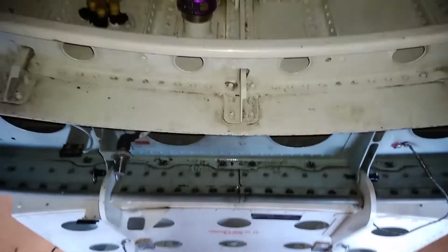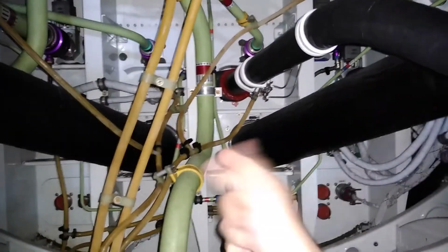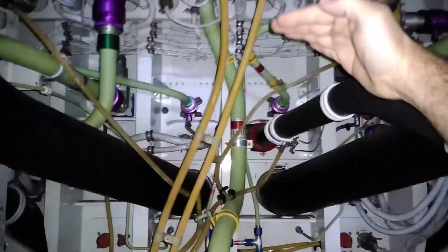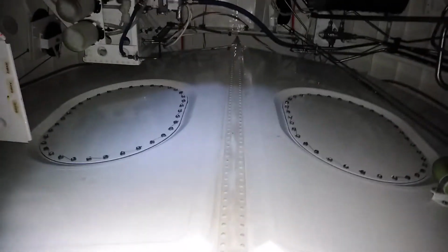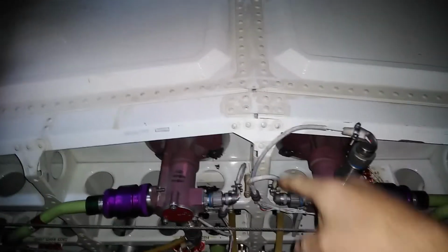Alright. Now we're looking forward again. We are inside of the aft equipment bay, up a ladder. This wall here, now we're facing aircraft forward. Left, right, forward. We're in the back of the airplane. And this is a pressure bulkhead, which comes this way, steps up, and continues up. All that is pressurized. That is the end of the pressurized area of the airplane. From there forward, inside of that is pressurized. From here back, it's not.